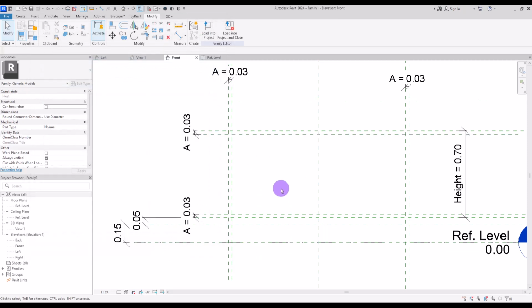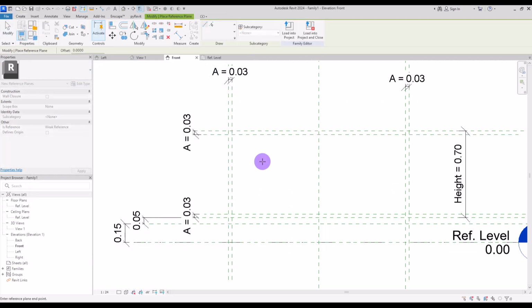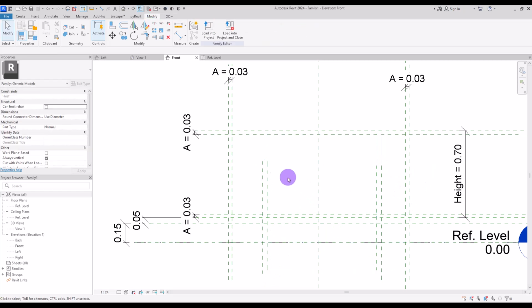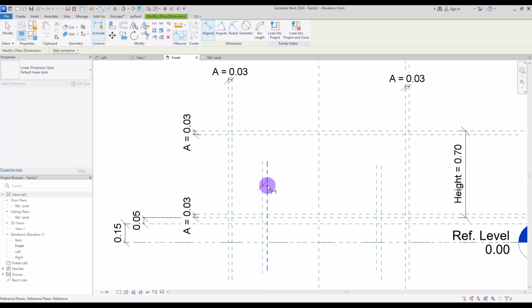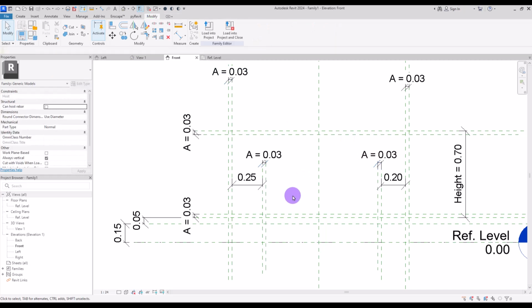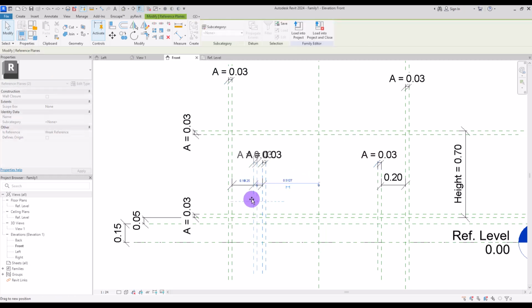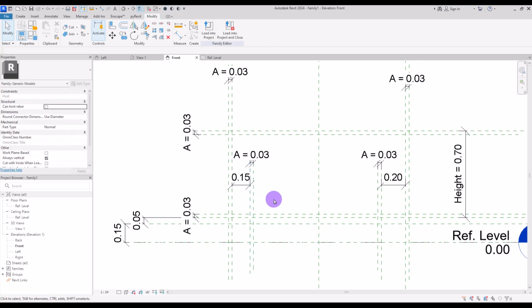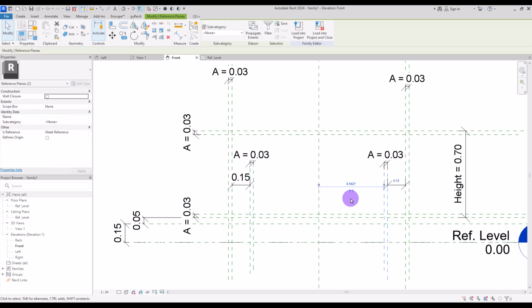Before drawing the shape, I'm going to add some reference planes in these two parts and also offset like this. This distance should be A again, and we can set their place by a fixed number from these parts. Select these two and assign a parameter for them. And for this part, let's move them closer and lock it. And repeat it for this part.